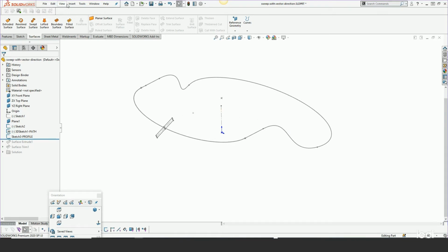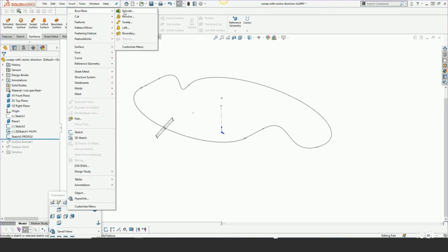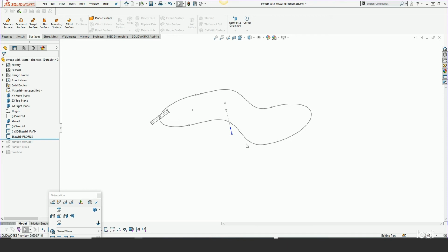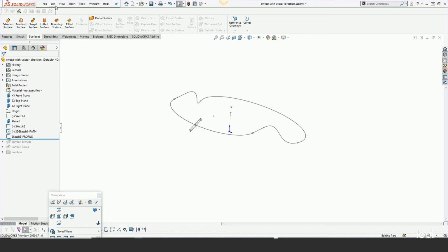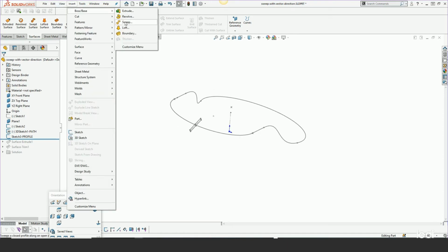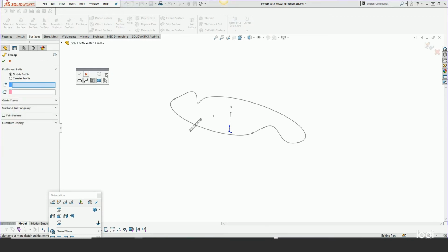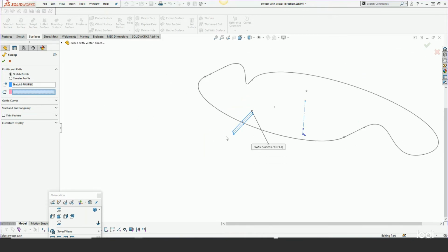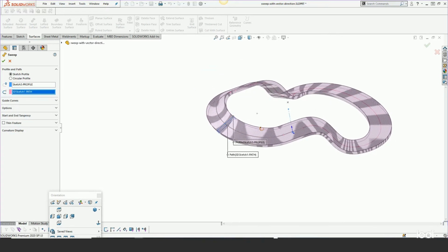Let's just say, for instance, this is the gasket that has to cover the opening of a pipe that isn't planar, but it dips down here. So we're going to create a sweep, and we'll use this rectangular profile, and then we'll use this as our path for that gasket.